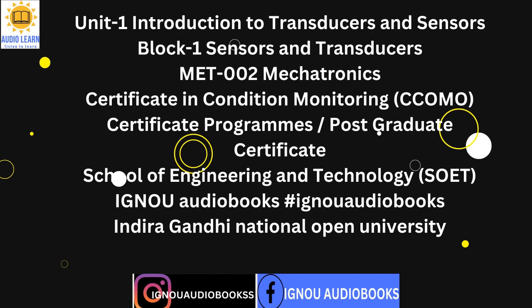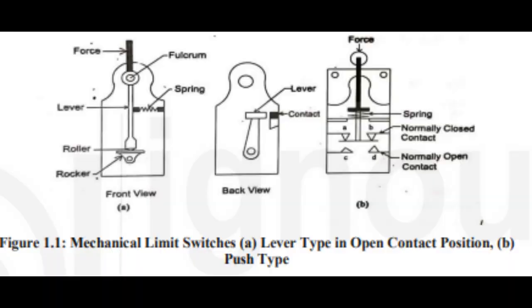Figure 1.1b illustrates the more direct action of a push-type limit switch. It shows a set of contacts operated from the contact lever assembly. Contact set AB is normally closed, set CD is normally open. When the lever is depressed, each contact goes to its opposite state. When installed, the user wires the appropriate contact pair back to the controller, which distinguishes the state of the system by reading the voltage or current, on-off, supplied through the contact.